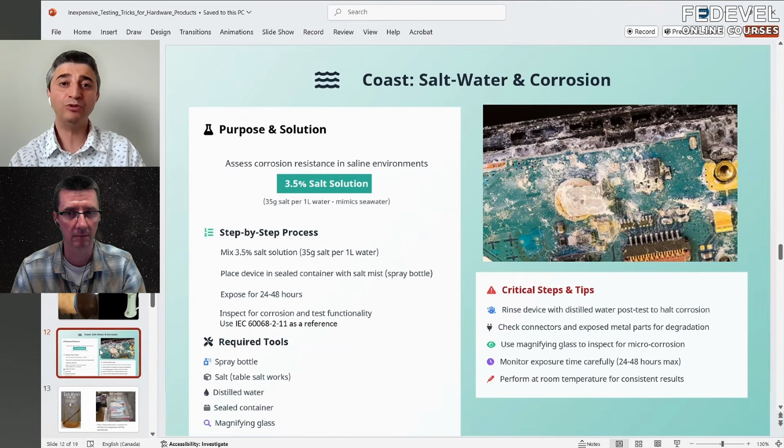One of the easy things people use for the printed circuit boards is to do conformal coating. There are different kinds of coatings where you can coat your components and maybe part of your connectors so that you can avoid this kind of corrosion if your product is meant to be used in these extreme environments. Some of the extreme environments, in addition to the coast, is basically industry like oil and gas. There are locations where they have high sour gas. So there might be another spray that you can do to protect or coat your parts, especially the connectors, against this sour gas that might cause corrosion.